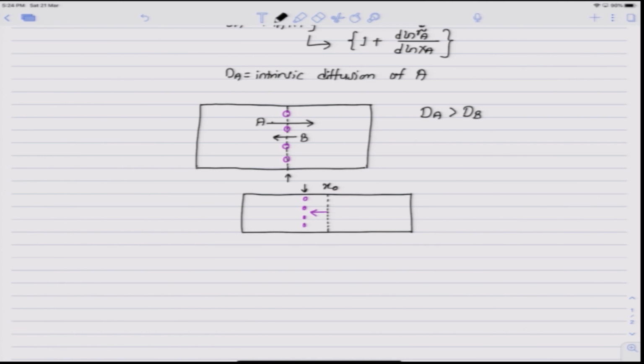The diffusion flux with respect to this frame of reference stuck to the lattice plane or the marker plane is referred to as the intrinsic flux, because it will give only the Fickian term, whereas if we measure with respect to the Matano plane, there will be a term also because of the drift that has been caused because of this lattice movement.